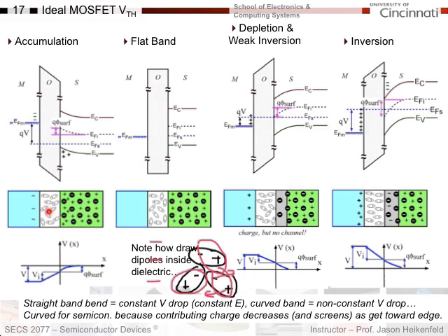little bit. And so if I look at how they've reoriented and transferred charge across the capacitor of the oxide, let's assume I have something, I'll draw it here. I've got negative charge here, and then that's on the metal, and then here's my oxide. Well, what happens is basically silicon dioxide molecules near the surface reorient a little bit, okay, such that they have their positive side here and negative side here. And then the next molecule sees the reoriented silicon dioxide.